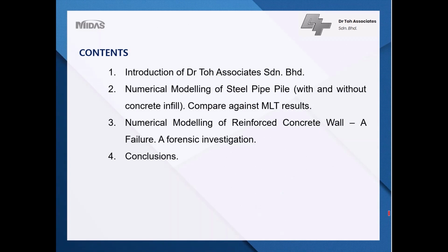This is the content of the talk today. Basically, I will share two project applications using Midas GTS NX. The first project application will be the numerical modeling of steel pipe pile with and without concrete infill. It is not the purpose of these presentations to show you the pile group analysis, but we take one step backwards to go into the fundamental of the problems to show you how to model the settlement behavior of a single pile in axisymmetry model and compare the result against the main test result.